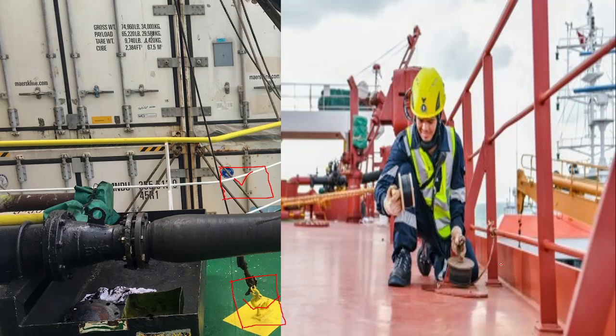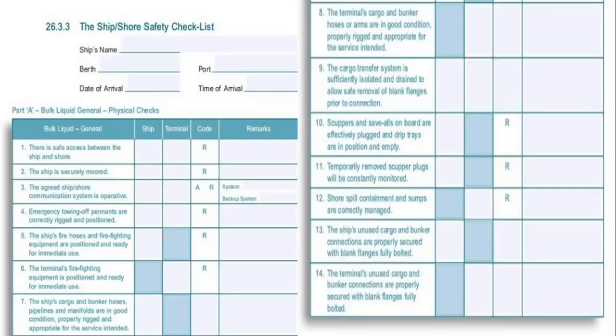The third and most important thing is that you should make sure that all the scuppers near the bunkering station are closed. Your drip tray, this is a drip tray, should be closed. All the drip trays of the bunker station should be closed. This you need to make sure before taking the bunker.